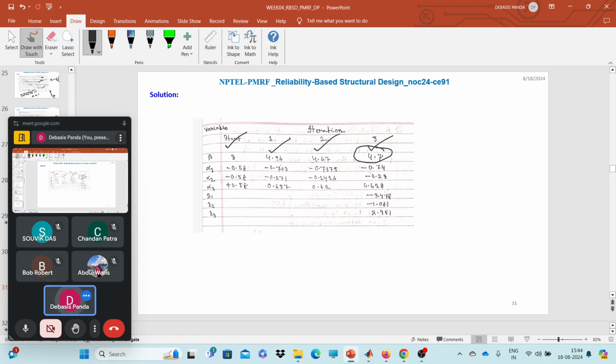Here I have put the tolerance, like you just subtract it, 0.003 something. When we solve the problem using MATLAB, we can set the tolerance as 0.001 or 0.002, so the number of iterations will increase. So this is your final beta equal to 4.7. Once you have found beta, you can find the probability of failure, phi of minus beta.